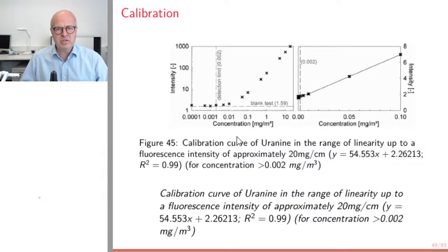Now, if people use this and it gets into your river or into the water cycle, you actually have uranine in the sample even before you do the experiment. Another reason can be that other hydrologists are doing trace experiments. Unfortunately, this is why there is a database of trace experiments in Bavaria and Baden-Württemberg. In some countries or states, this is not the case, and this can lead to interference with previous experiments.